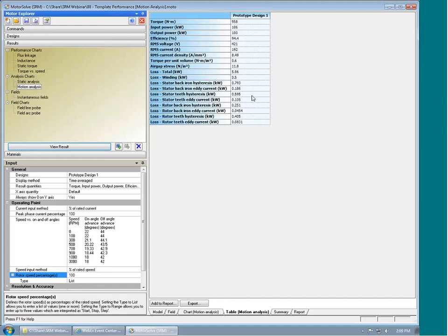So this is very instructive because this helps to tell you which are more important with regards to the frequency and the drive, and to help clarify for us what we might want to do to reduce the flux densities or to modify materials and to optimize with respect to our flux density versus the generated losses that we might have. This underscores the capabilities of our switch reluctance motor technology in MotorSolve.